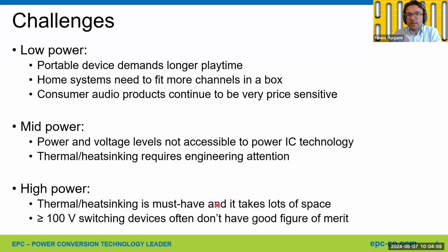So the higher the efficiency of the amplifier, the smaller can be the heatsink and the size of the product at the end. And also, most likely, the voltage rating of the power devices is above 100 volts, so the 150 or 200 volt rating, or even higher. And the main challenge is that in case of silicon MOSFETs, those higher voltage devices struggle with switching performance.